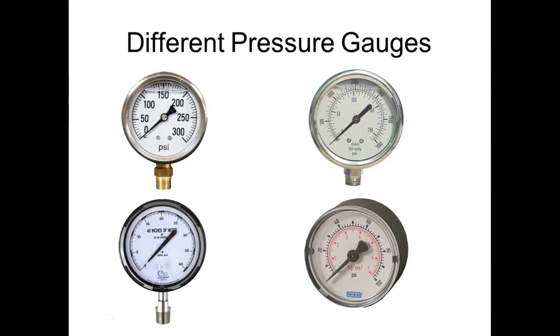But what I was thinking is, some of these robots or whatever are made in foreign countries, and if they have gauges on them, we need to know how to convert ours to something that we can use. Right, or replace the gauge, whatever we need. Most of these threads are pretty standard size. So if you have a gauge out there that's in bars, you could very easily go get the same gauge that's in PSI and just replace it.